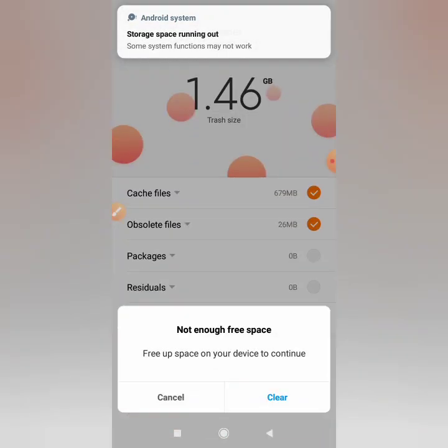I'm discussing the process. First step we have to follow: find the center of gravity of the given load system from the right and check which load is nearer to the center of gravity. I will discuss it with an example so that you will understand this better. Find the distance of the center of gravity of the load system and the nearer load D. First I have to find the center of gravity of the load system. I'll try to find the center of gravity from the right.